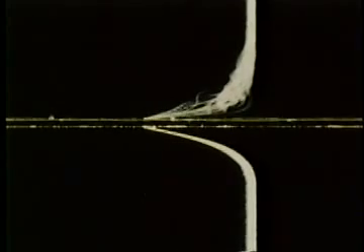Superimposing a number of displacement lines enables us to obtain a mean velocity profile for the turbulent layer and the laminar layer, and at the same time gives an experimental notion as to where the fluctuations occur and how large they are in the plane of mean motion. In this photograph, we can compare mean laminar and turbulent profiles. Here is the laminar one, the turbulent one. And here they are superimposed.